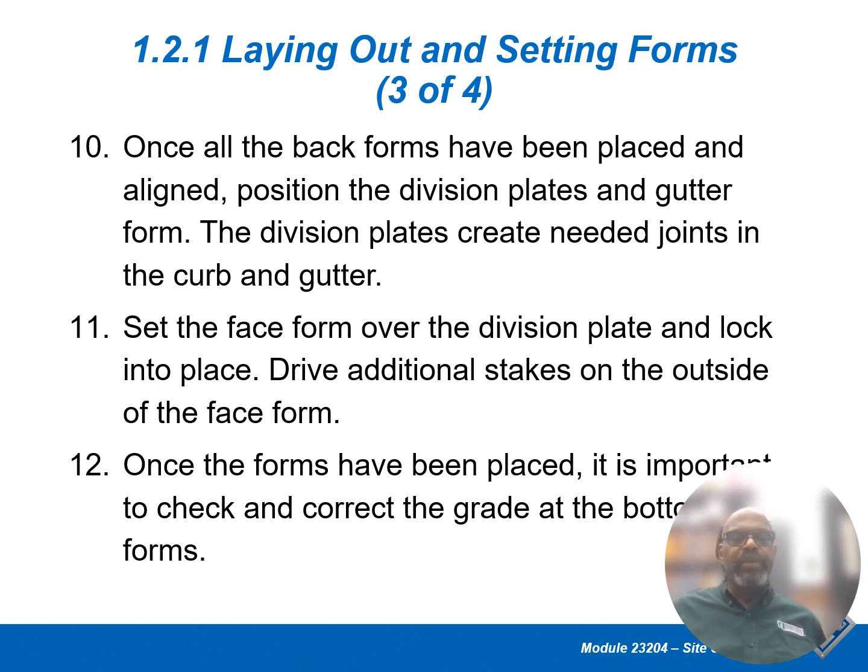Once the forms have been placed, it is important to check and correct the grade at the bottom of the form, because you don't want to be adding any more concrete or have concrete leaking paths, where there could be a void where the form is at. So make sure the ground is level and graded out correctly.